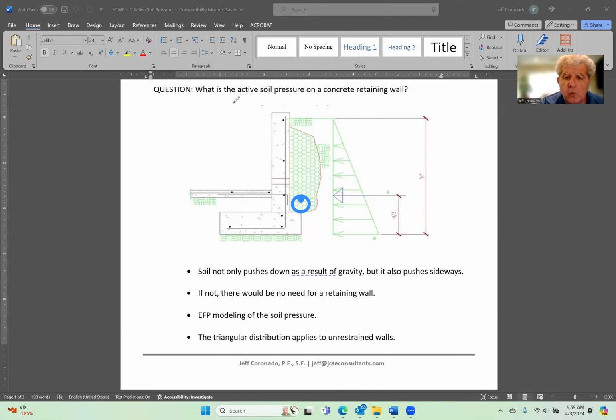So that as the water collects here in the soil and starts to push against the wall, it will migrate down just through gravity, and it'll get into the perforations, going into that pipe, which then the water will run away. Obviously the pipe needs to have a slope, right?